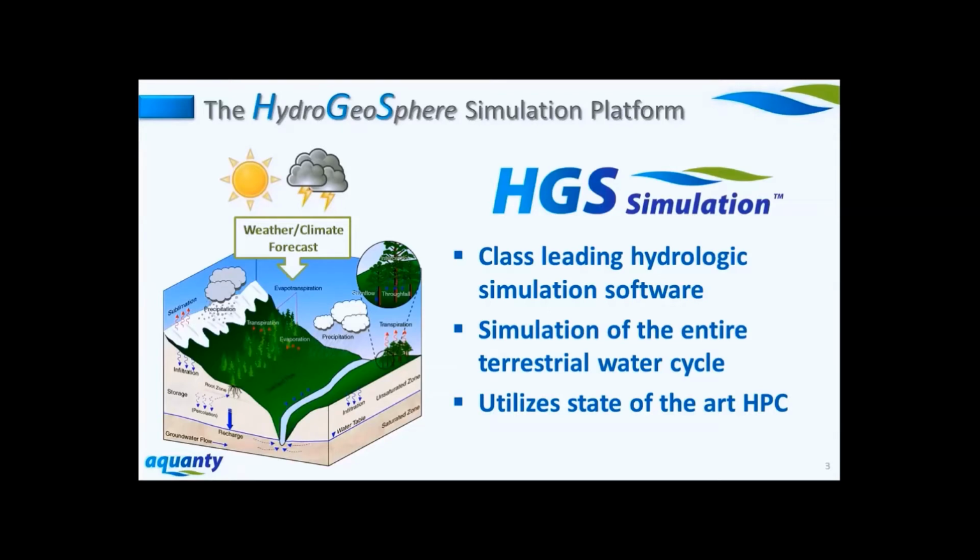Now, we are interested in many cases not just in the movement and storage of water, but also for example, solute transport, groundwater contamination, etc. So over the land surface, we solve the two-dimensional form of the advection dispersion equation, and in the subsurface, we solve the three-dimensional form of the advection dispersion equation under variably saturated conditions.